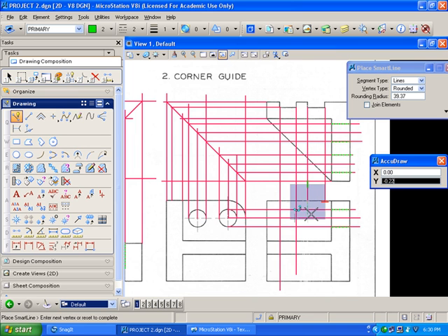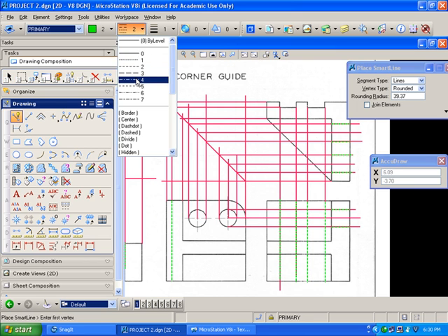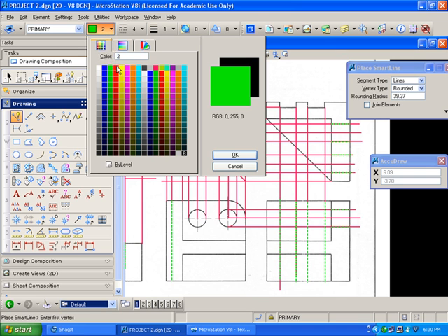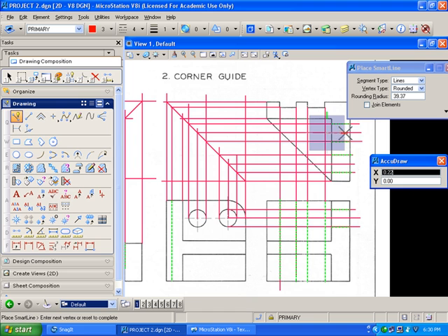We've got some vertical slots that go all the way down through here, and here, one here. These go all the way down through, and if we extend this line over and down, the back of those slots would actually show up right here. We can change to a center line, line style 4, and we'll just put a center line here and here and here. Let's turn off our construction lines again,